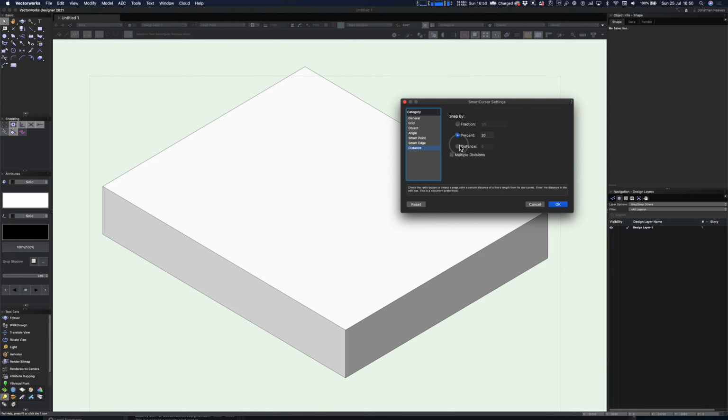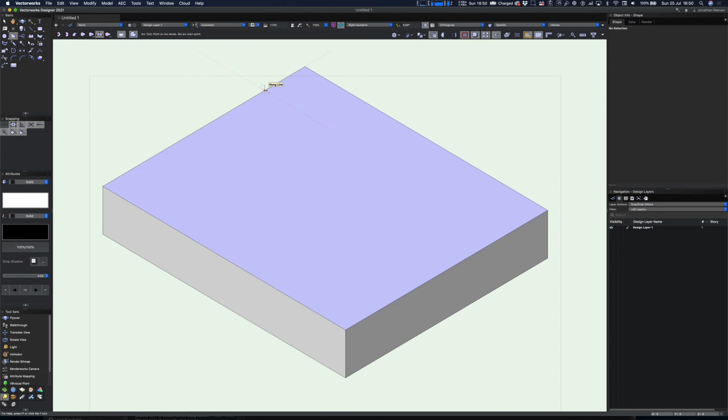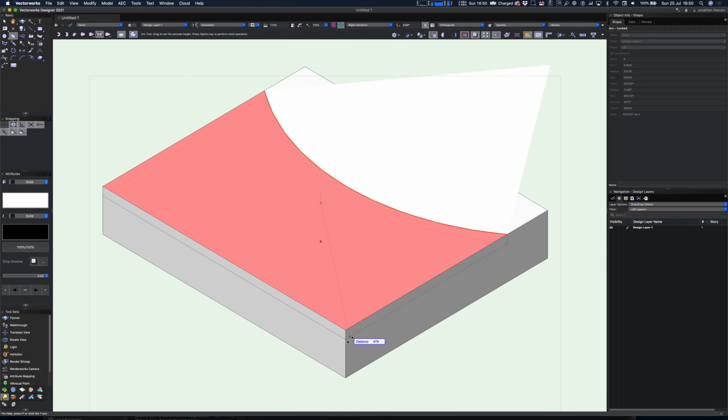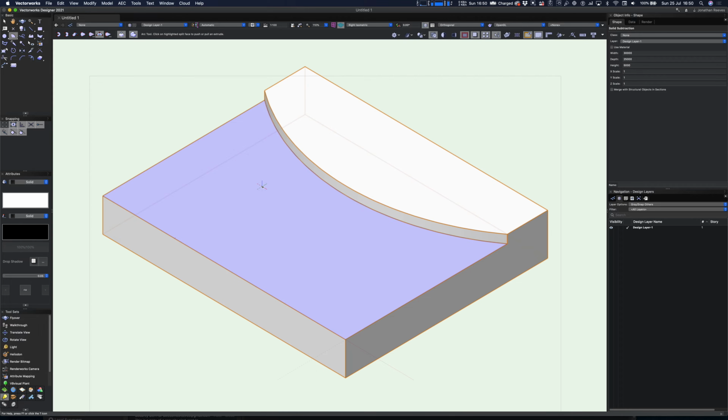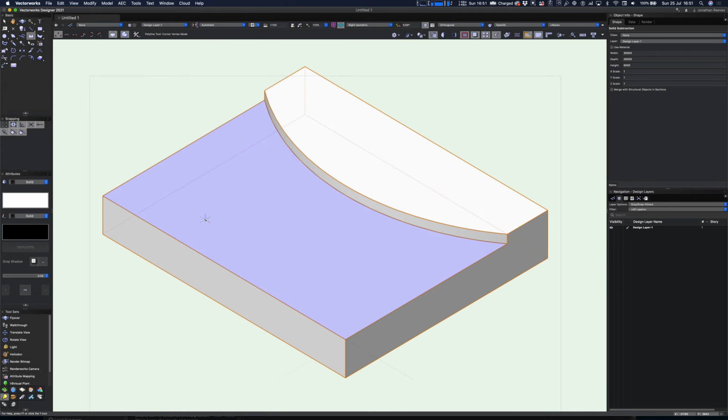You can see that I'm double clicking onto the snapping palette. I'm just going to change the distance for snapping to be 5 meters. So what this means is every 5 meters along the edge of the shape, you'll get these along line snap points now. So we can easily subdivide the shape, clicking on there, and I'm doing this with an arc as you can see, and basically I'm going to click on that surface, let's come out another 5 meters, and then I can basically click and push and pull using that arc to split the surface of the form. Now that's really cool, really nice easy way to create some steps.